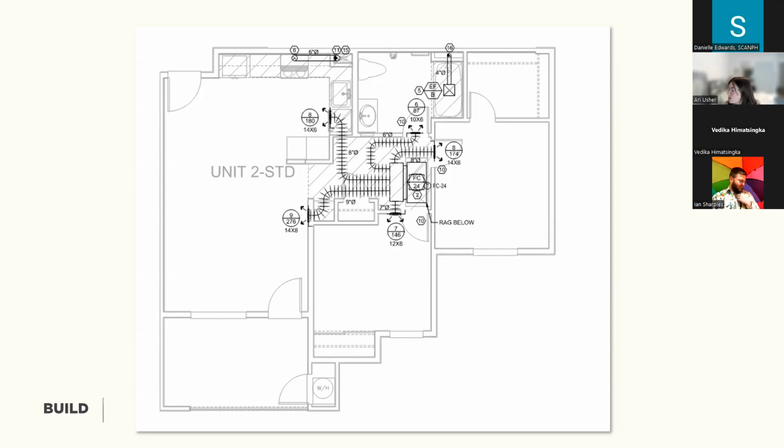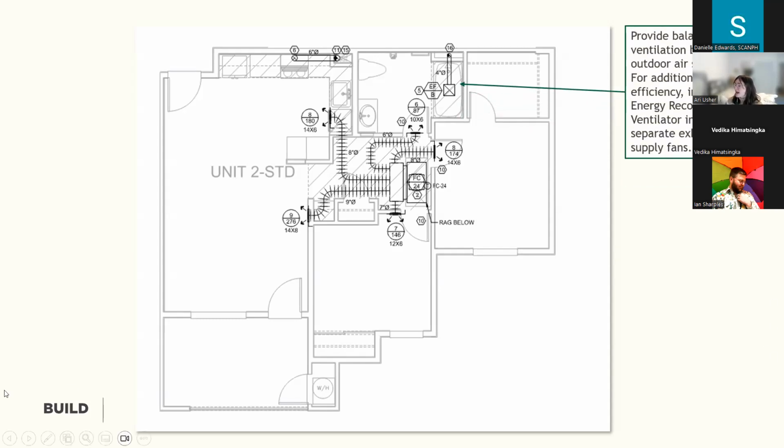And that is the only ventilation fan in this unit. So indoor air quality could be improved by providing balanced ventilation rather than exhaust-only ventilation. This is going to make the unit more healthy by bringing fresh outdoor air into this unit.